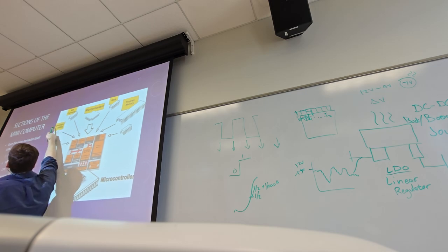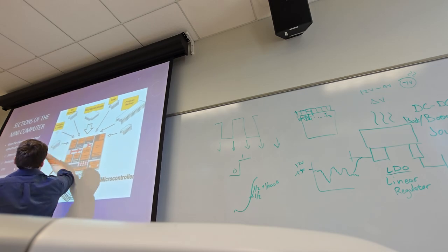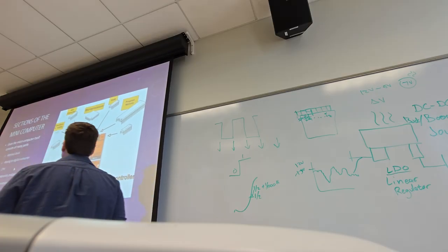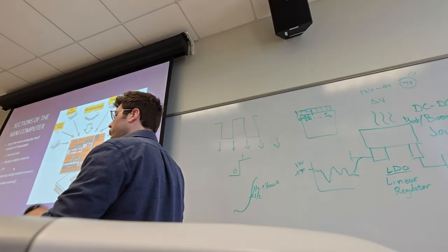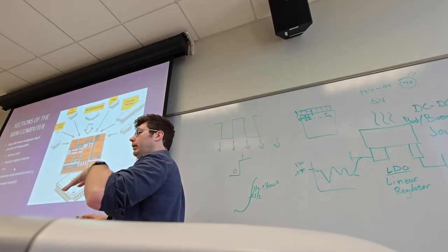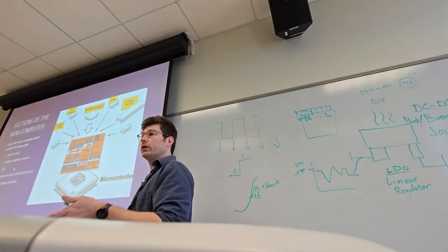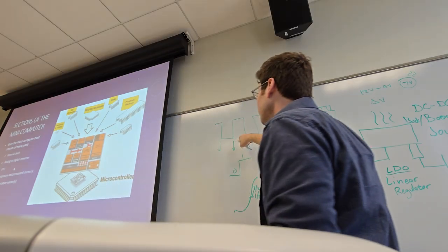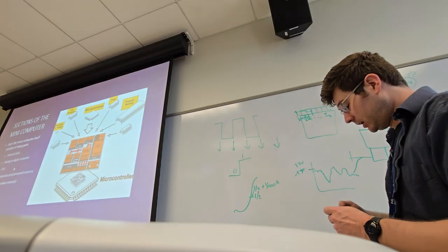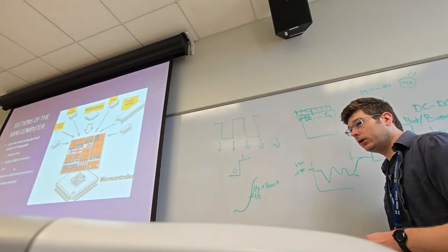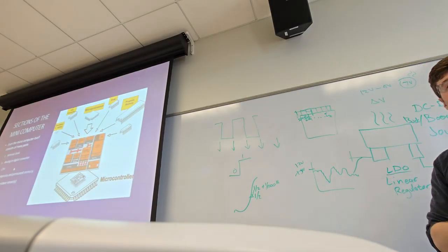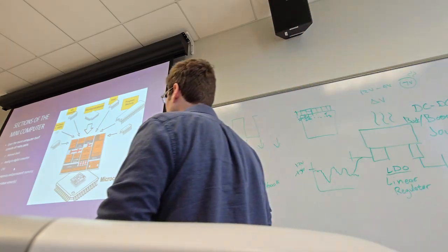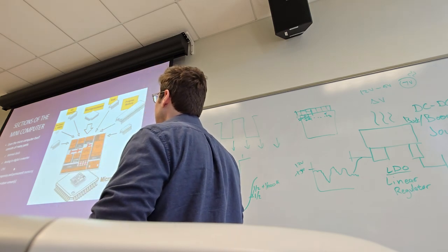And so what it consists of, very often it will have another timer in it or another oscillator, one or more oscillators. So there's an external clock and an internal clock. Oftentimes external clocks are temperature compensated. So clocks will drift over time. It's why clocks will gain and lose seconds, for example, is that if this square wave is supposed to go up and down at 12 million times a second, and it goes at 12 million point 0.00001 per second, it's going to drift over time as it moves to and fro, as the temperature changes, as pressure changes.